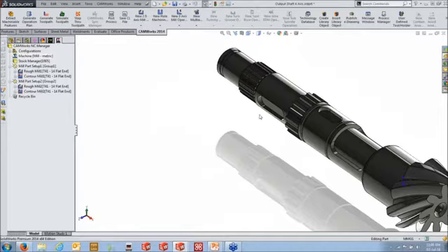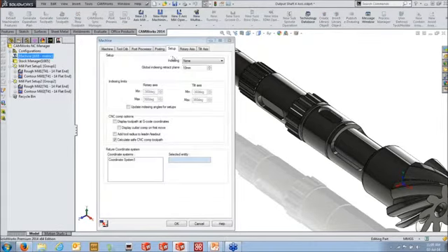And the way we actually control the indexing between these is using the machine limits. So we set the machine limits up in the machine tab up here. So we go into our setup option and say we're using 4-axis, and then I set my rotary axis limits here. Now what this is going to control is actually the different solutions available.